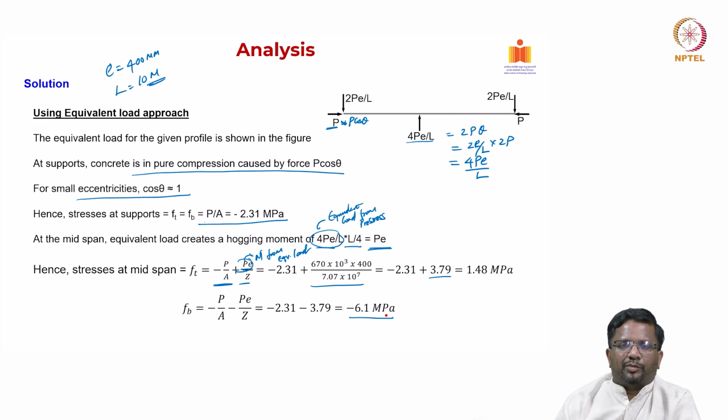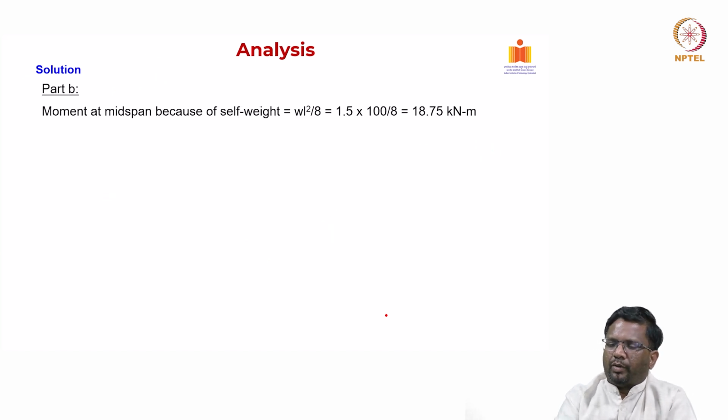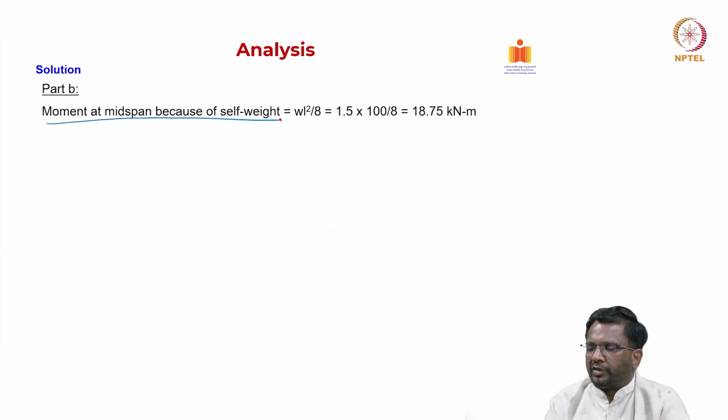Again it has to be the same. It does not matter whether you do stress analysis, force analysis, or equivalent load analysis; everything will yield the same, because they are all statically equivalent approaches. So, you will end up with the same stress magnitudes. Now, let us go to part B: what is the moment at midspan because of the self weight?